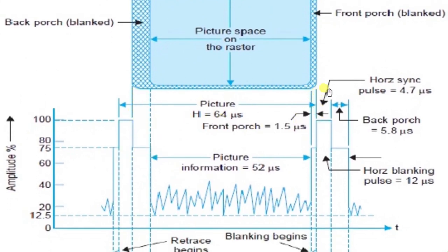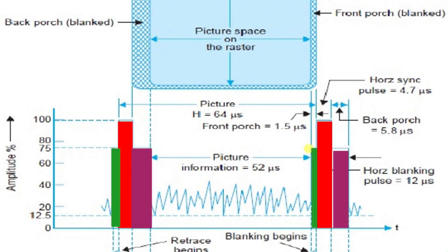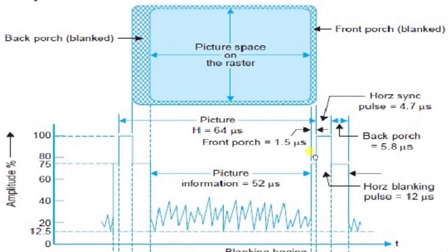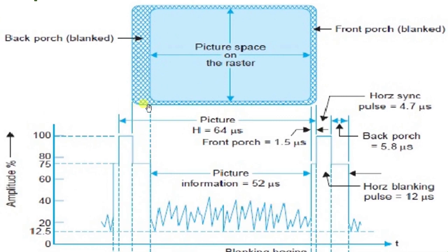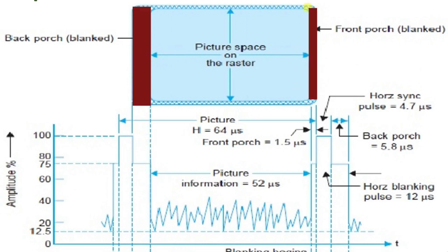See Table 7.1. Horizontal blanking details, time period in microseconds. Total line H 63.5, H blanking 9.5 to 11.5, alignment pulse H 4.75 plus or minus 0.5, front porch 1.27 minimum, rear porch 3.81 minimum, visible line time 52 to 54.